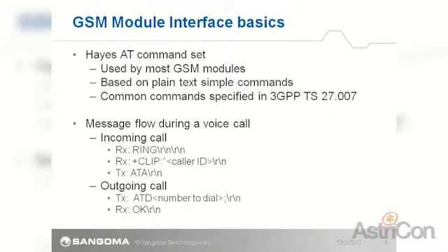The next thing was going quickly through GSM module interface basics. Most of the GSM modules out there use the Hayes AT command set. It's a plain text, simple command line based interface.